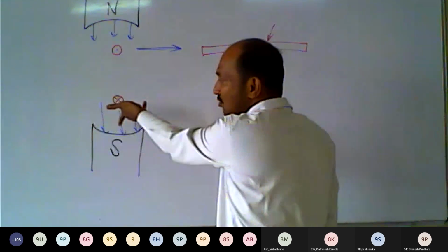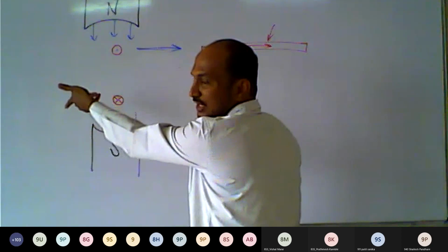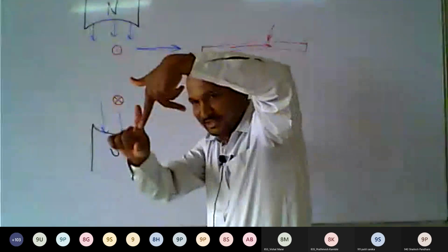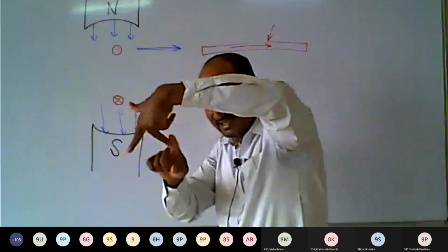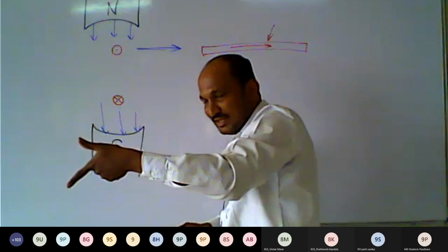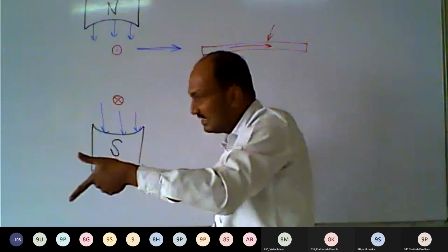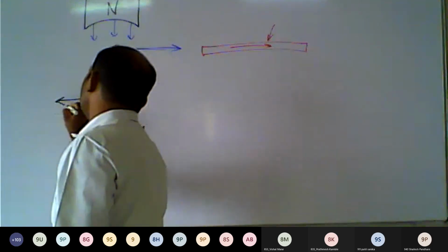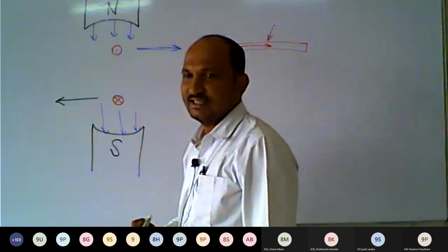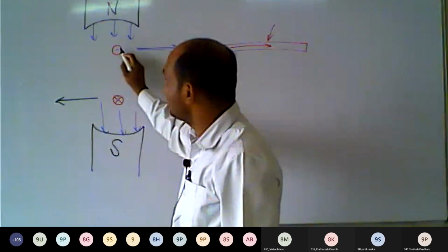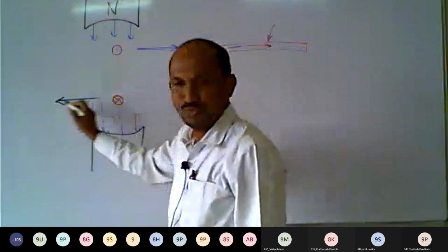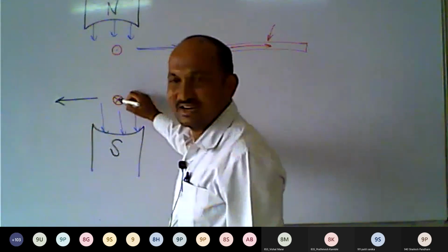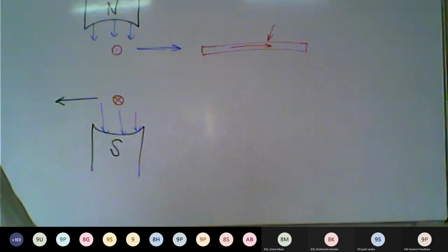So in this case, this conductor will move towards the left side. It will not move to the right side. It will move to the left side due to Fleming's left hand rule. Apply it again: this indicates the direction of flux, this indicates current, and the current is away. In this case, the thumb indicates the direction of movement. So this conductor will move to the left side. Due to Fleming's left hand rule, this conductor will move to the right side and this conductor will move to the left side. Here electrical energy in the current carrying conductor is converted into movement. Movement is nothing but mechanical energy.